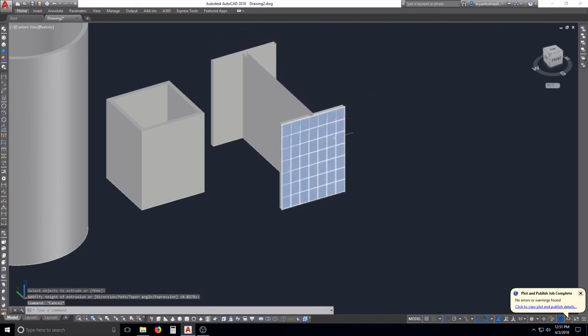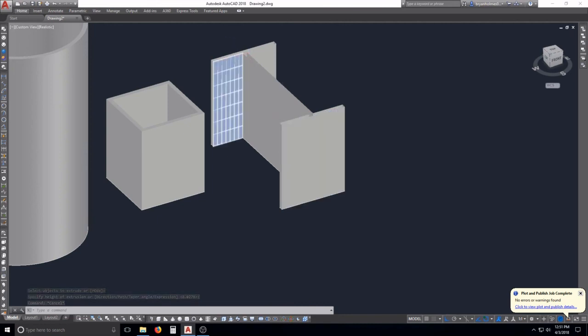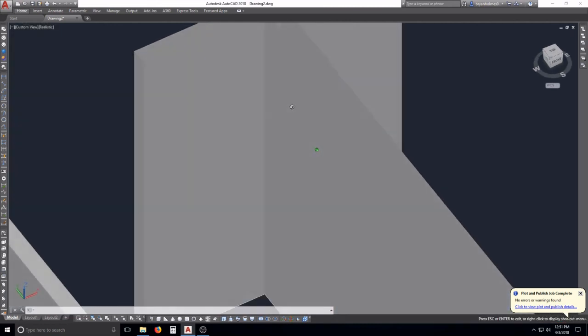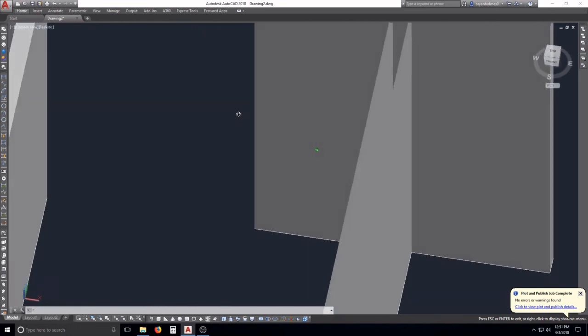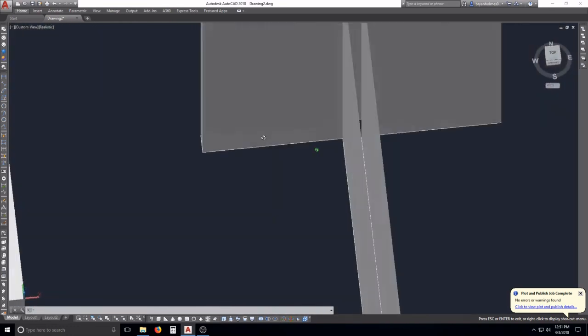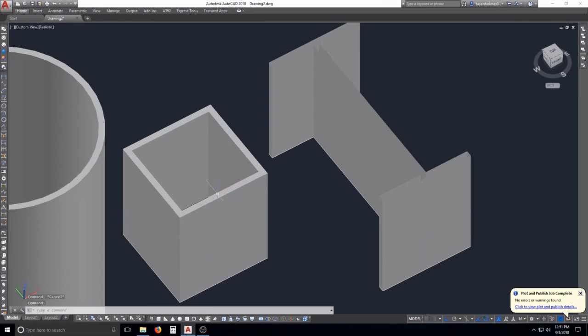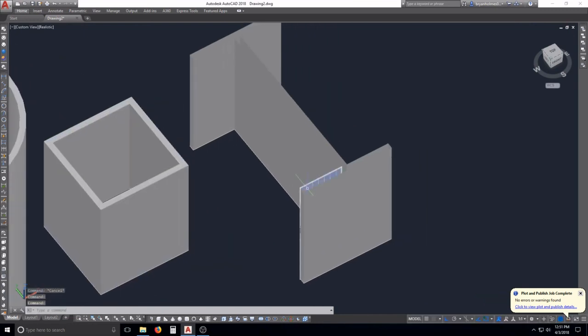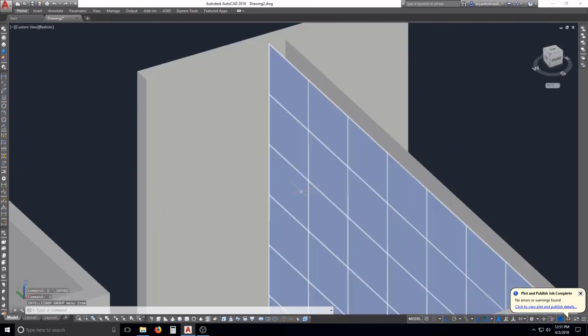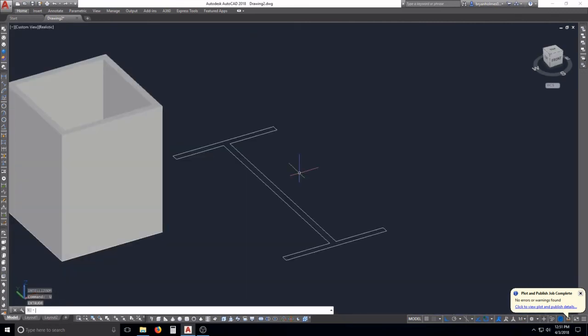Guys, really big. So what this did, guys, is turned it into mesh. See that? If you shift, middle click on your mouse, see it's hollow in there? Everything's hollow. Has no volume to it. The neat thing about using solids is if you get into using some of the in-depth things of CAD, AutoCAD, your 3D stuff, I'm undoing everything to the point of where that was solid again, back to a polyline.